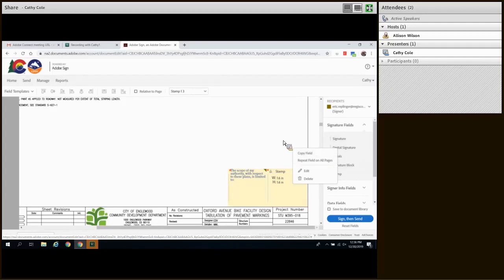So one last thing to say before I send this set of plans to Eric to seal. It is the responsibility of the local agency's person in responsible charge to know and ensure that a record set is signed or sealed properly. In the past, the design engineer of record didn't have to know exactly which engineer signed which page, but now you need to know. If you set up someone to sign the wrong sheets, you have to start all over again.